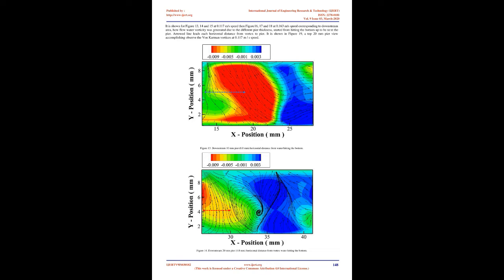Finally, the video was recorded with a CCD camera, taking 40 images of 24x24 pixels at 700 microseconds. The videos were processed by LaVision DaVis 8 software, from which data were obtained in DAT format. The DAT files were post-processed by Tecplot 360 software to obtain images, whose final result was the average of the 40 of them, formed into a video.